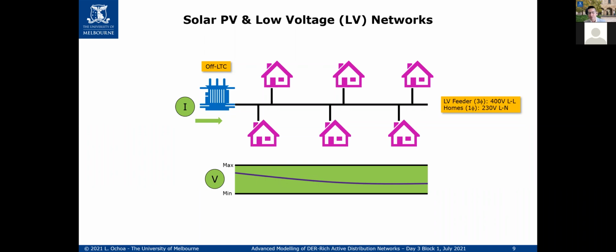So of course there's reactive power and other things, and so you end up with a transformer that is the next highest, right? So let's suppose it's a 40 kVA transformer, and then that's it. That's how you design the transformer. And then the cables, perhaps it will be, depending on the part of Australia that you are, depending on the number of houses there and the spacing that you do per house. Perhaps it will be, I don't know, 200 meters, 100 meters. I mean, 6 houses must be 100 meters, just a street. And then you size the corresponding conductors and everything.